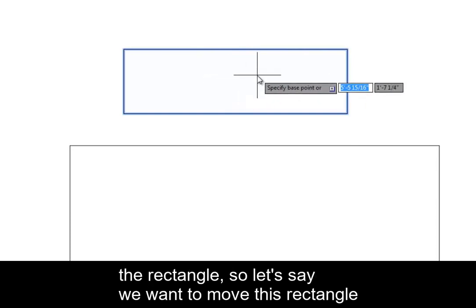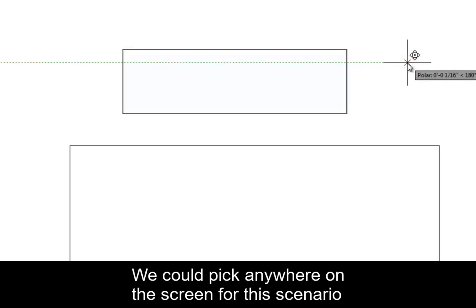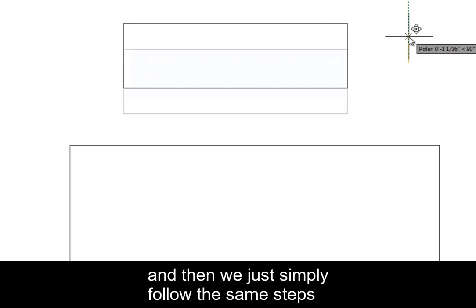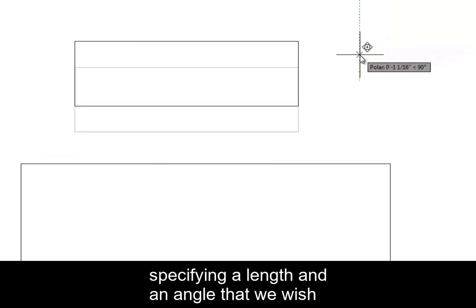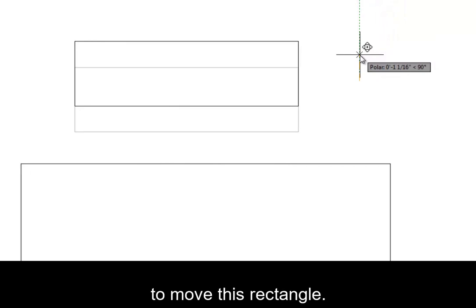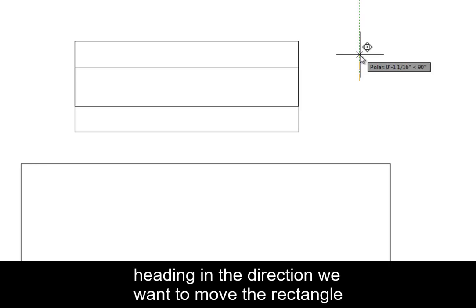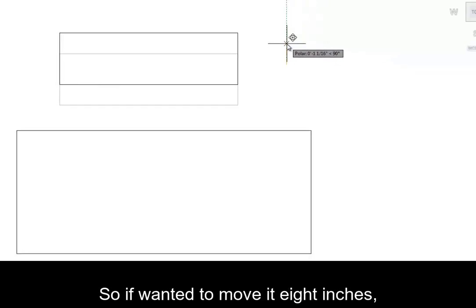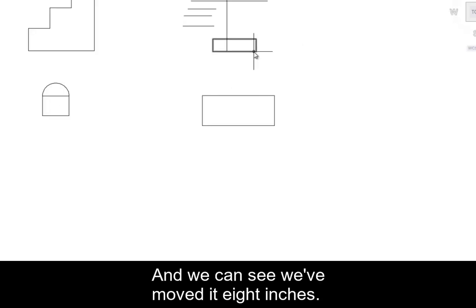So let's say we want to move this rectangle 4 inches straight up. We could pick anywhere on the screen for this scenario, and then we just simply follow the same steps we followed to draw a line, because basically we're specifying a length and an angle that we wish to move this rectangle. So we pick our first point, snap to the vertical, heading in the direction we want to move the rectangle, and then we'll type the distance. So if we wanted to move it 8 inches, we'd type 8 and enter. And we can see we moved it 8 inches.